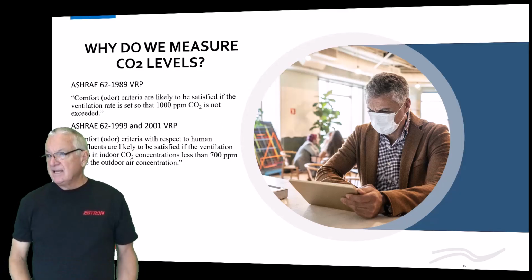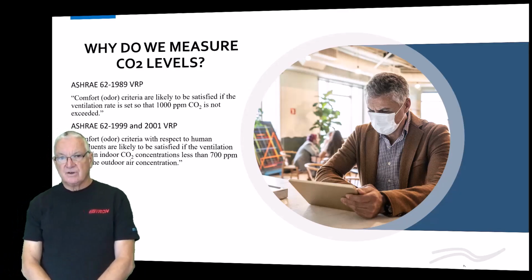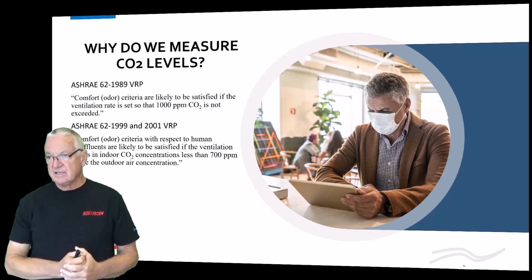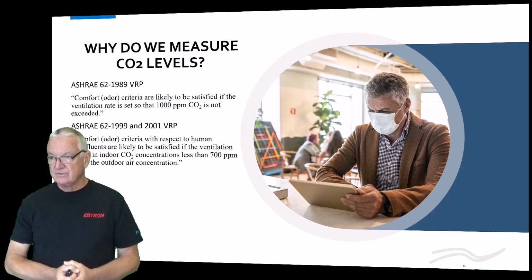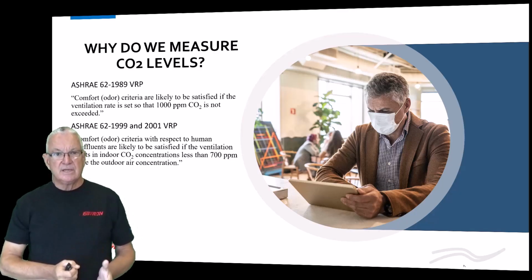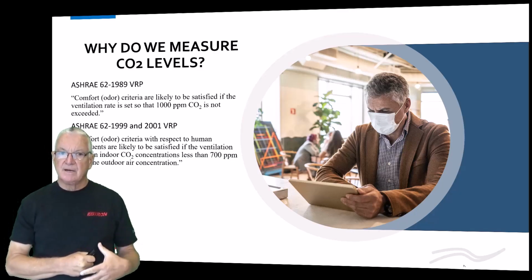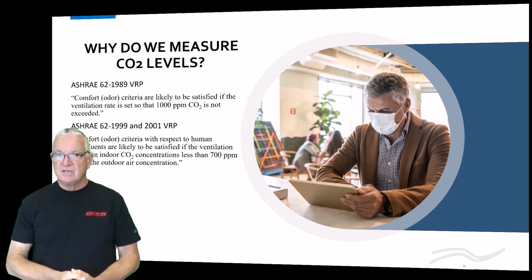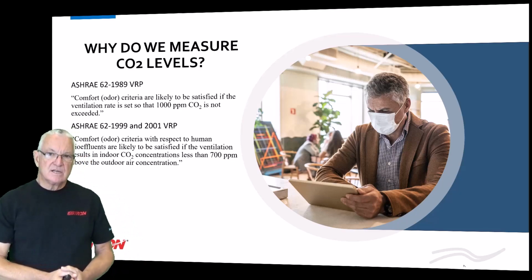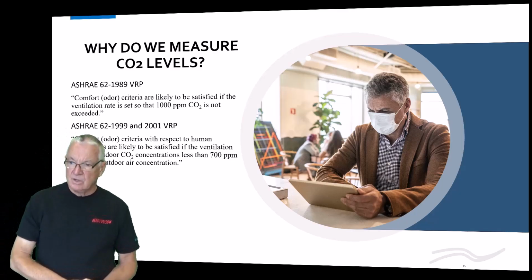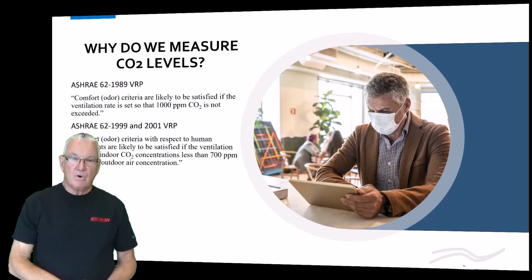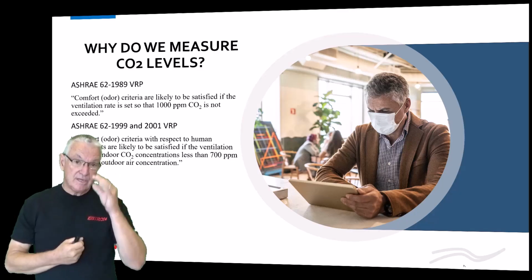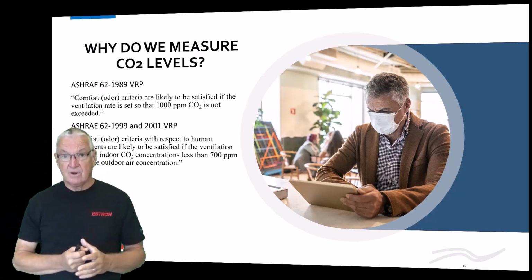Now I think that gets us to the point where we need to ask ourselves, since so many people are doing this with CO2, and as you're going to see, Standard 62 has actually incorporated some language for CO2 recently, why are we doing this? Because there's a lot of misunderstanding about the role of CO2. When you measure CO2, what is it all about? Over the years, I've talked to a lot of people who say CO2 is a measure of indoor air quality, almost like treating it like it's a contaminant. And it's really not. That's really not why we're doing this, and you really need to understand why it is that we're doing it.